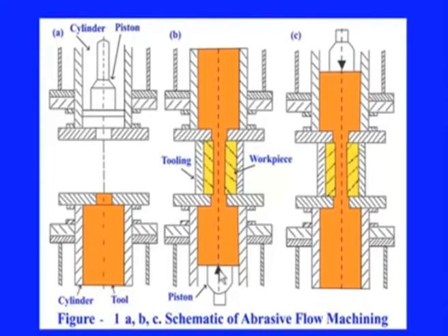Then, as this media is completely pushed through this passage and the other cylinder gets filled, in the subsequent process the media from this cylinder will be pushed back to the next cylinder and the process will be repeated to and fro like this for several cycles, depending on the accuracy required, the surface finish required, or the material and so on.